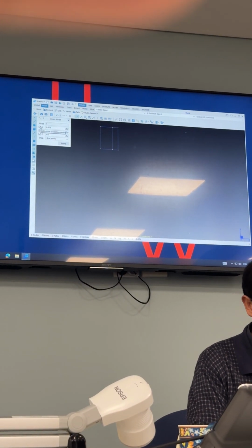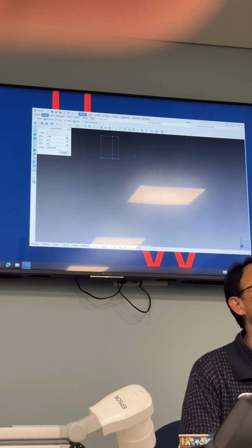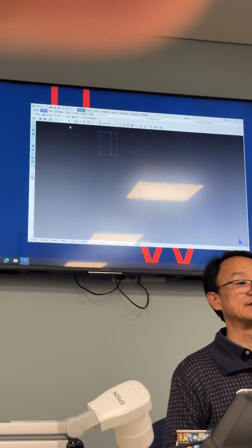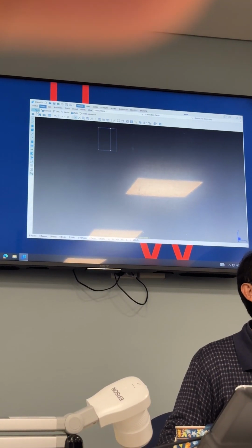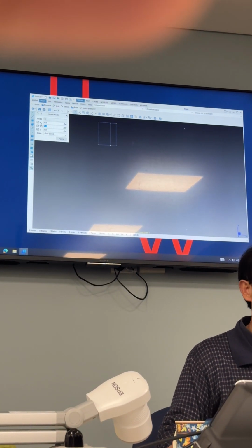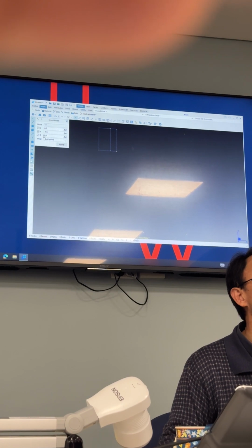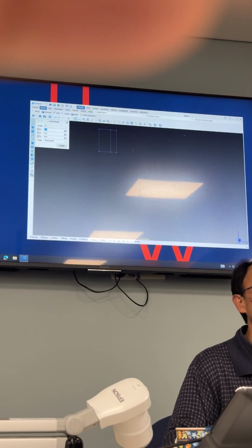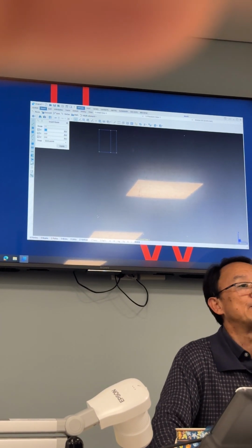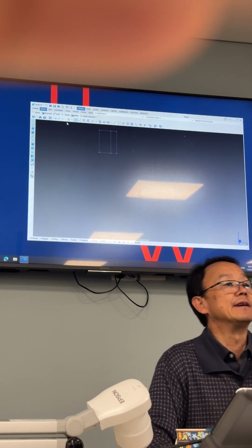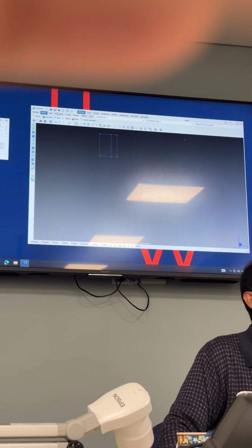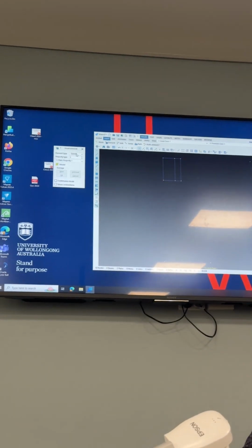I imported the coordinates of the points. You see the value of the coordinates when applied. These are the points. I still miss a point. Okay, I imported this point, this point, this point, and this point. After I import these points, what am I going to do? I'm going to form the element, element by element. So Visual, Insert, Element, you choose quadrilateral 4. You got it?